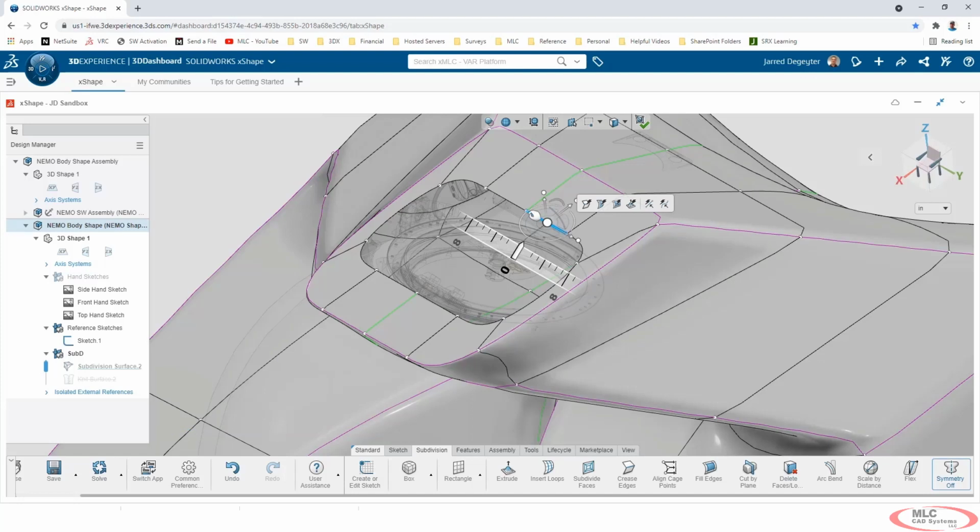And what this is going to allow me to do is it'll automatically select all of the open loop that I'm working with. And in our case, what we're interested in doing is matching up those entities that we have selected with the sketch that I've created from the hatch. So I'll select both of them and take a look at what we can do from here.